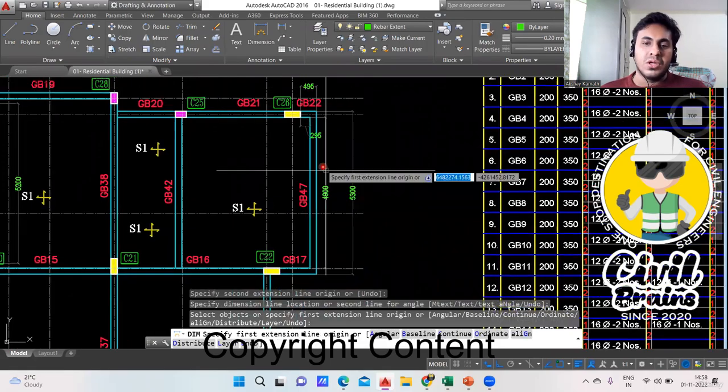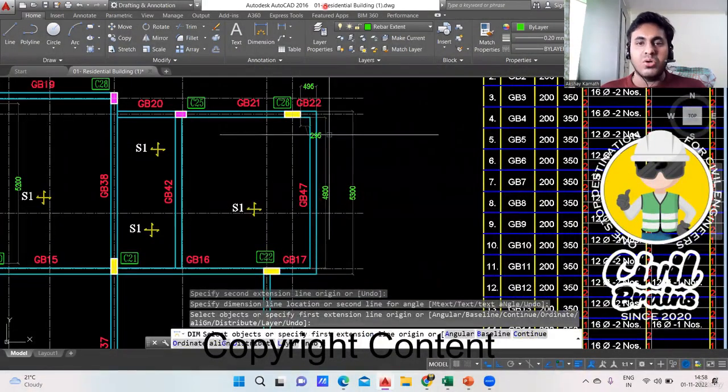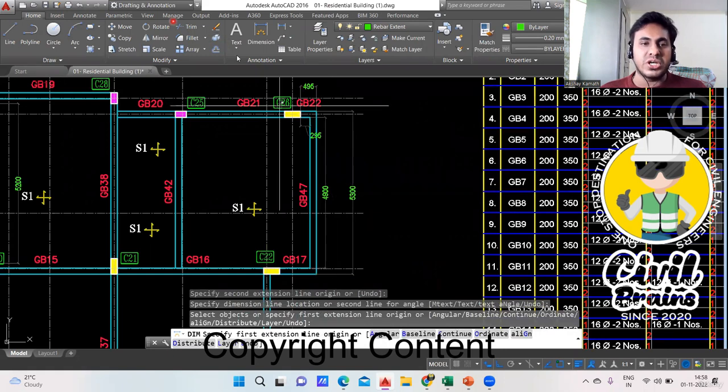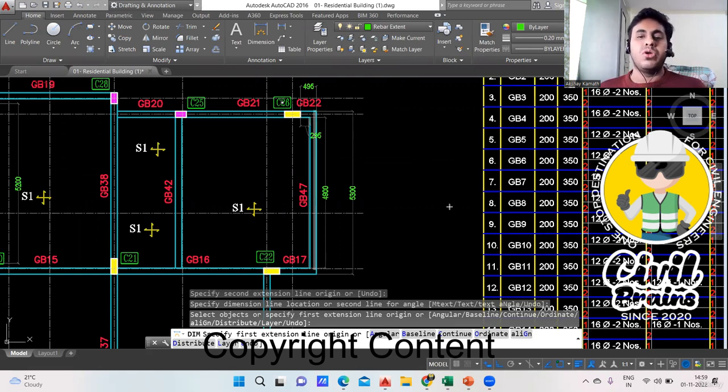Yeah, come here. See, when you have such kind of beams, how do you take care of that? So in this beam, what has happened? When you do the concreting, your concreting will be complete from here to here. I agree with that. But when it comes to the shuttering, how will it be? Your shuttering will be one part here. This will be an outer shuttering. And for this, you'll do only this much shuttering. Okay.